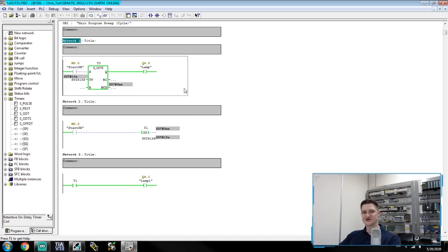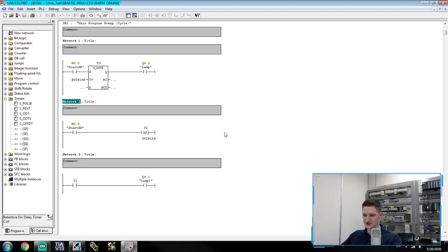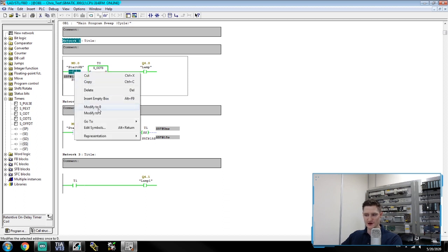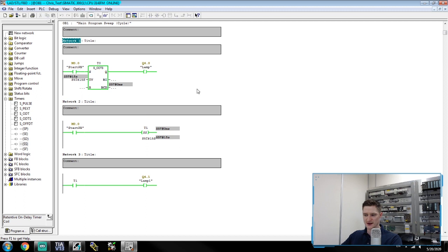And these timers are slightly different. These timers are what they call latched on or retentive timers. They don't need the input signal on for all periods of time. All it needs it on for is one PLC scan. Now you'll notice with these timers, both output coils are on, both timers have elapsed, but how do we turn off the timers? The signals are already off. If I switch that back on, nothing happens. If I switch it back off, nothing happens. It still remains on.